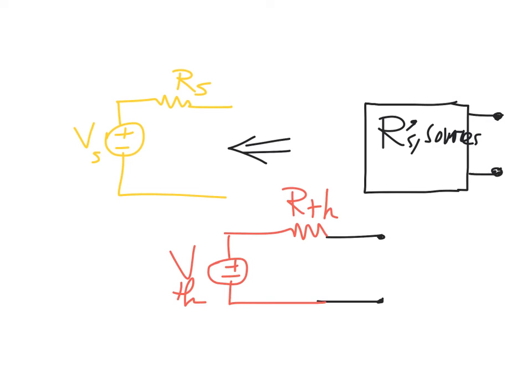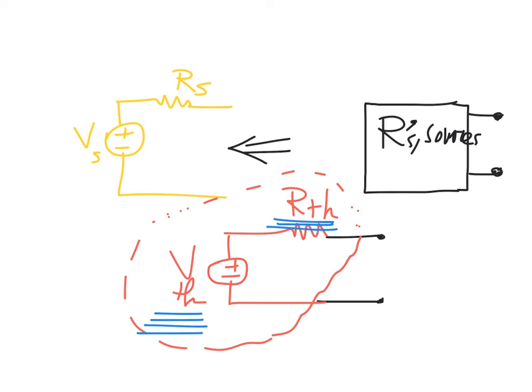So this circuit can be representative of any complicated circuit you can imagine. At the end, this complicated circuit can be approximated or simplified or modeled as just one source and one resistance. If you want to deliver a specific value to your load, just add the unity buffer here.